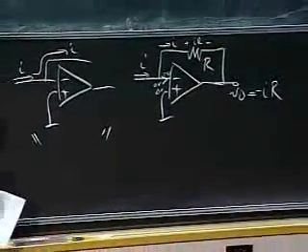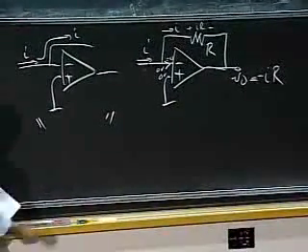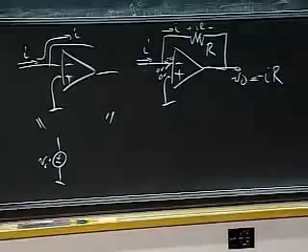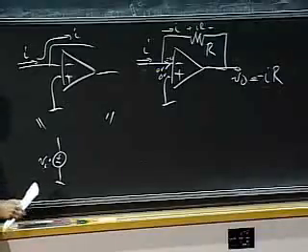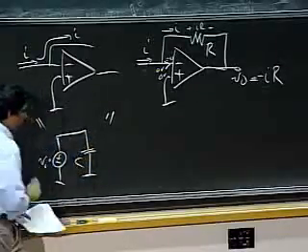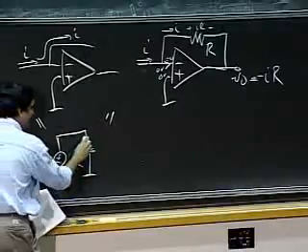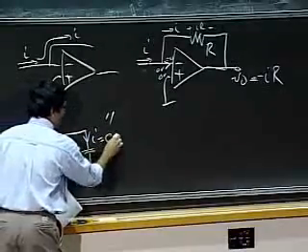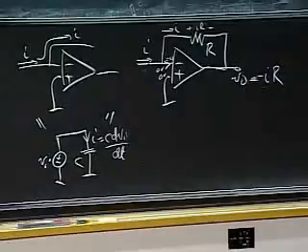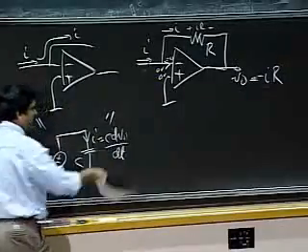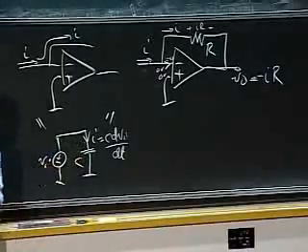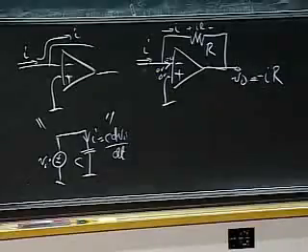Abstractly, what I need to do, again, this is design here. So we'll talk about abstract stuff. Like if I have a voltage VI, I need to produce a current which relates to C dVi dt. And I know I can do that by simply doing this. By doing this, I know my I is C dVi dt, correct? So I'm looking for a pattern where a voltage VI is directly applied across a capacitor, and when that happens, the current relates to C dV dt.